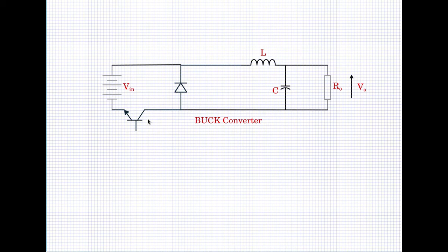Now this is still the same old buck converter. The operation is exactly the same. When this transistor is on, the Vin potential comes across the diode, turns off the diode, and charges the inductor, and the voltage across the inductor is Vin minus Vo during the dTs period. And during the time when this is off, there is no current flow here.